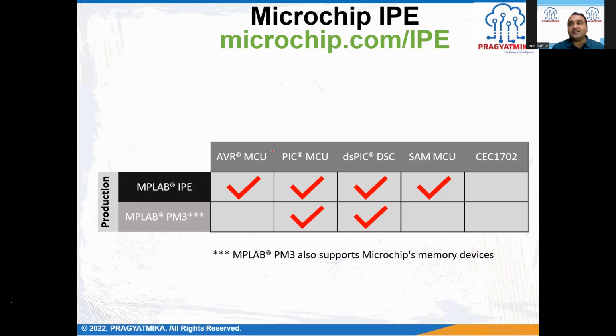Then it is the IPE. So that was the IDE, Integrated Development Environment, and then we have the IPE, the Integrated Programming Environment. MPLAB IPE is there for all the microcontrollers except CEC, because CEC has a proprietary programming feature. So that's why IPE is not there for CEC. But MPLAB IPE is there for all the AVR, PIC, DSPs, SAM, all of these. MPLAB IPE is used for R&D purposes. Once you are designing products for R&D, where you have to program each and every microcontroller one by one, at that time it is better to use the IPE.